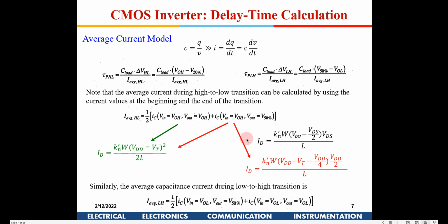So what is the gate voltage? If you see, yes, it will be in saturation. Correct, because the gate overdrive is 1 minus 0.6, 0.4 volt, whereas half VDD is 0.5 volt. At the output, VDS will be 0.5 volt because 1 volt is the VDD. So I will have 0.5 volt across the drain, so it will be in saturation, whereas the overdrive voltage, 1 volt minus VT, is 0.4 volt.